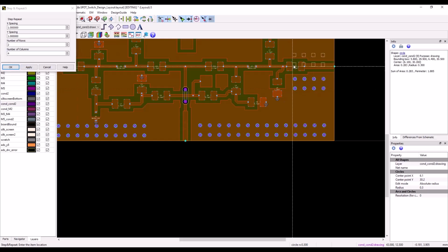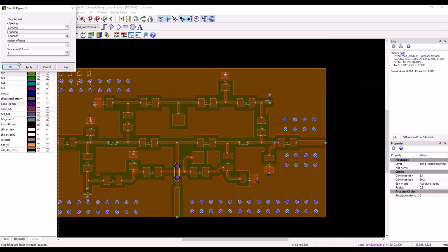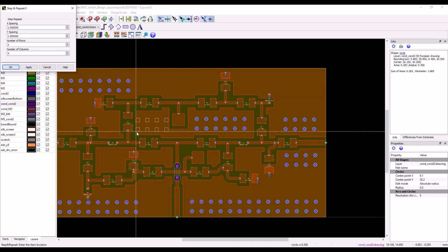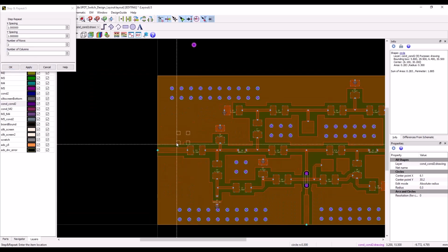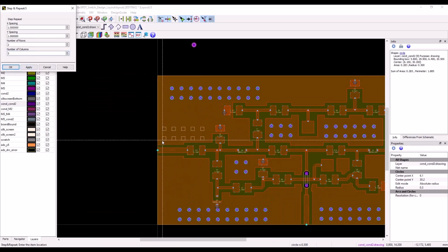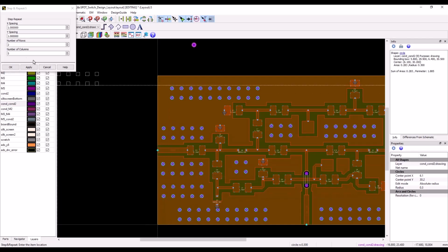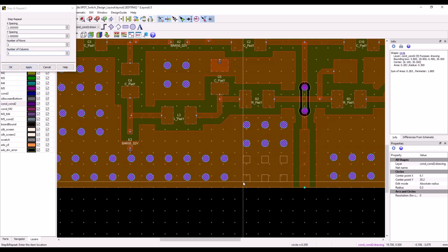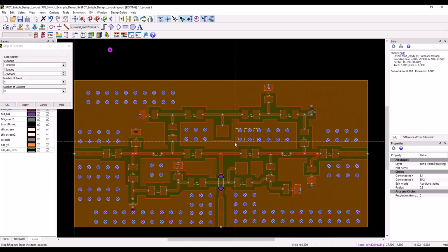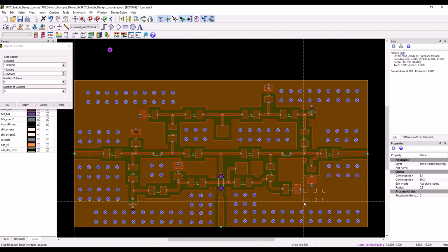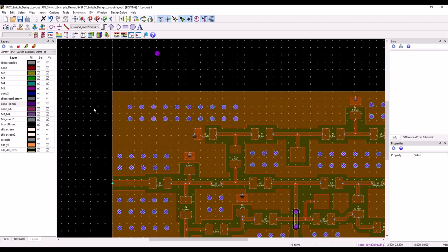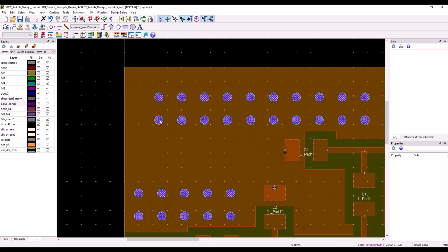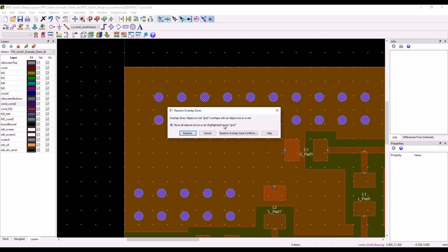By doing this process, once you place the layers, you can notice there is a minor blue cross in each of these circles, and that's happening due to the net mismatch, because the vias which we are placing don't have any net name, and the ground which we poured has a net name called GND exclamation. So we will resolve this as we go along, but let's go ahead and place as many vias as we want across the ground plane to make sure we have no parasitic capacitance kind of getting formed as a parallel plate between two layers.